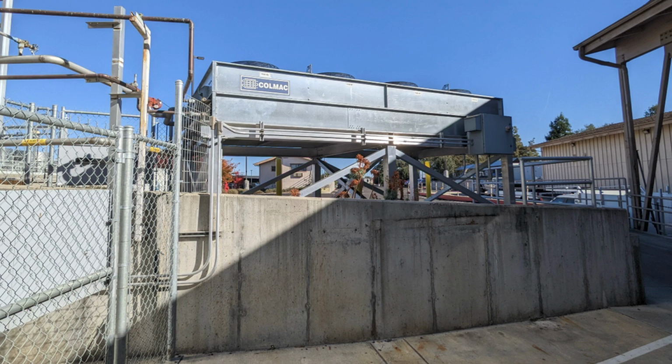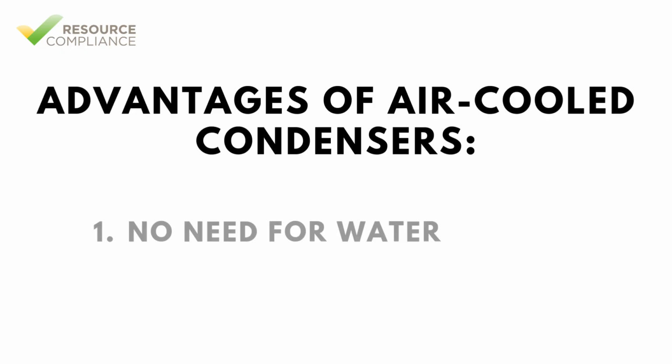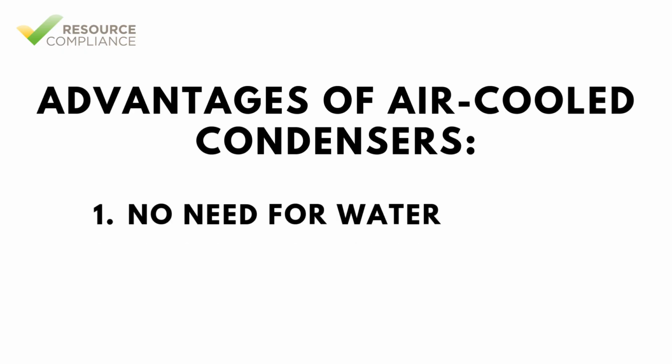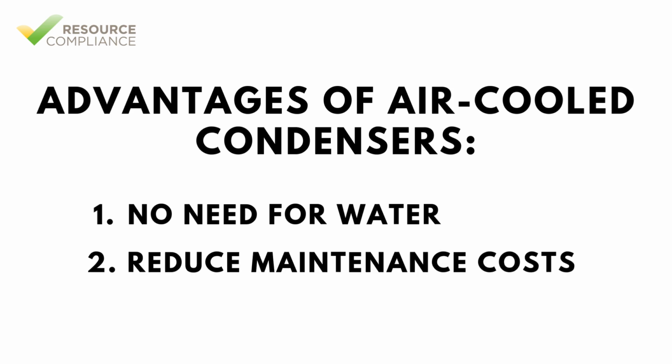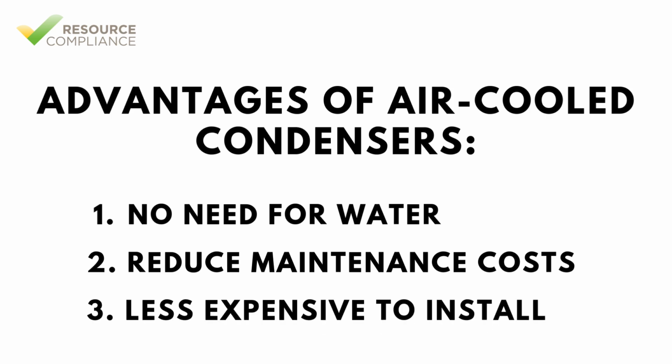The advantages for air-cooled condensers are fairly straightforward. First, air-cooled condensers do not require water. This is ideal in areas with limited water availability or where water conservation is a priority. Second, without the need for water, issues like scaling, corrosion, and water treatment are eliminated, reducing maintenance costs and complexity. Third, air-cooled condensers are less expensive and simpler to install compared to water and evaporatively cooled condensers.